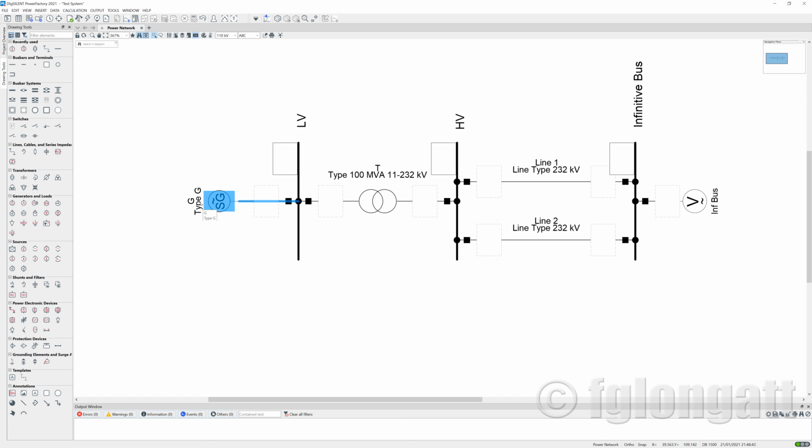And the most basic simulation that you can run in this system is the load flow, okay? I highly suggest every time that you finish creating your system, the best way to assess if the basic data is properly working is just running a static analysis, running a load flow and checking your results with the theory, okay?